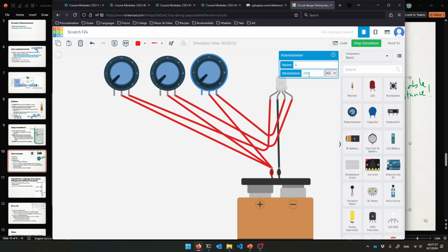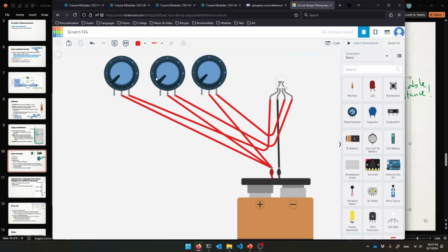I guess it doesn't really matter, but let's do 1,000 ohms for each. That's what I did in my example in my notes. You can still break your LED this way. You should probably be resisting before this cathode, but I do not care. We will break our virtual LED, it's okay. So yeah, I'll do 1 kilo ohm, or 1,000 ohms, for each of these.